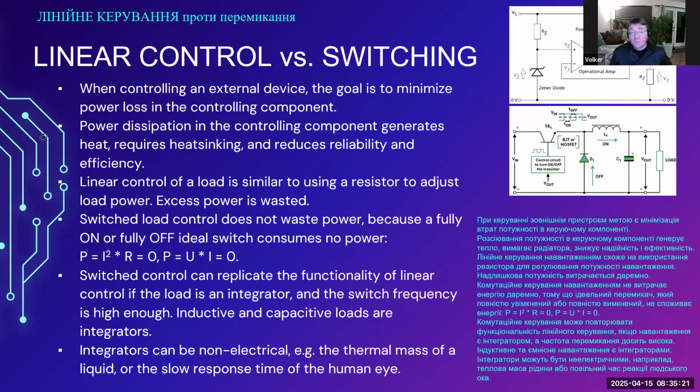It is enough for a very small relay. It is enough for a buzzer if needs to be. But even then, in most cases, even a buzzer will be operated by an additional switching device, by an additional amplifying device. Why do we use switches, or why is our goal to switch external components, instead of providing, for example, a linear changeable voltage to these components, if we want to change the speed of a motor, for example?